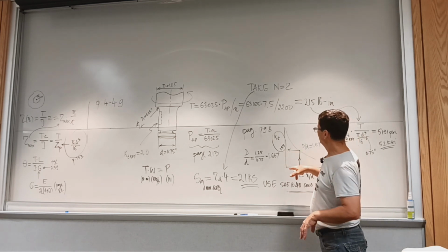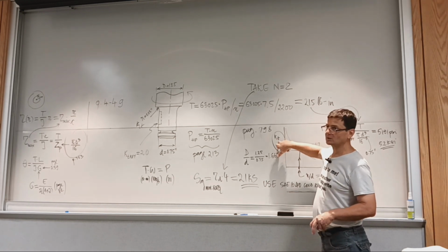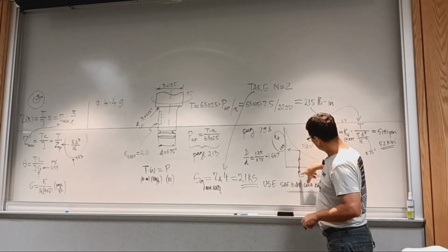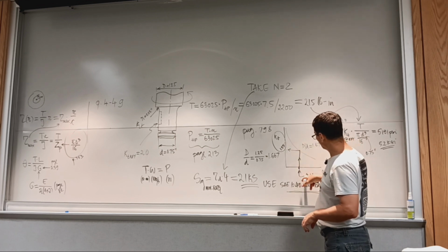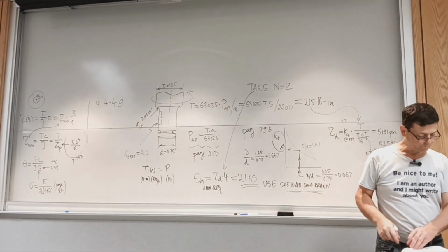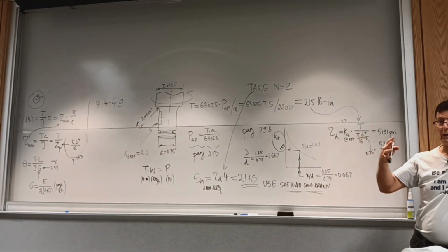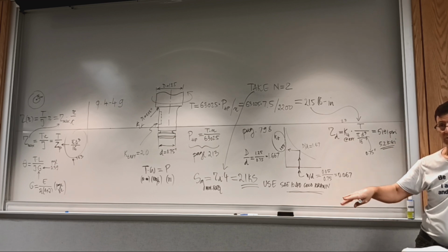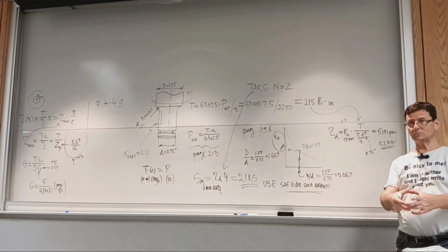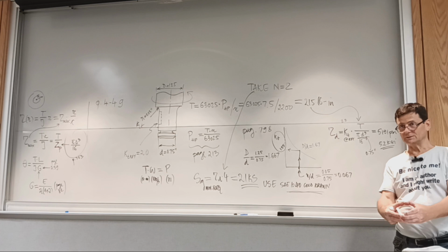So you calculate the maximum allowable stress concentration factor due to the hole. You read the ratio between the hole diameter and the shaft diameter, and you report the hole diameter. Of course, it has to be rounded to the nearest size, but you round down. Does it make sense? The maximum possible may be a fractional number, but you go with the next available drill size down, not up.